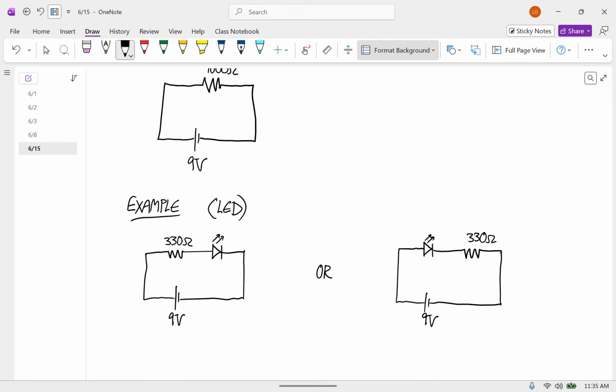The better way is to look around the rim of the LED, and you'll see that over one of the two terminals, the rim is flattened. It's like it's clipped off or sanded or something. It's not very obvious. You have to look pretty closely at it. But if you just rotate that around, you'll get to a point on the rim where it's flattened down.